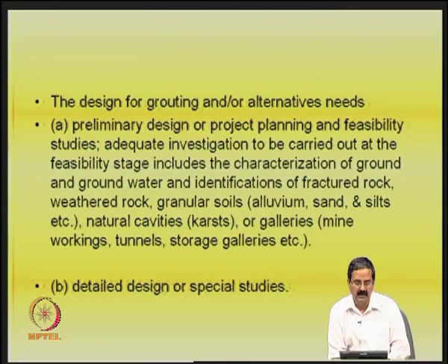You should also be able to know about the degree of weathering of the rock. Granular soils also should be known. For example, what is the type of soil you have, alluvium or sand or silts, etc. And you should also have information about natural cavities and galleries like mine workings, tunnels, storage galleries. There could be many things like openings that could be there underground. One should be very careful.